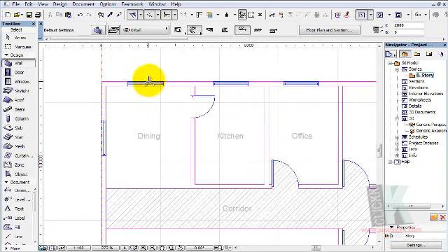So okay, what we're going to use here is a continuous wall. So let's mouse over back here to this section of the geometry method and choose wall continuous. Okay, now that I've chosen continuous, the next section here that I'll be editing is the wall height, the elevation. What's the maximum elevation for this project?